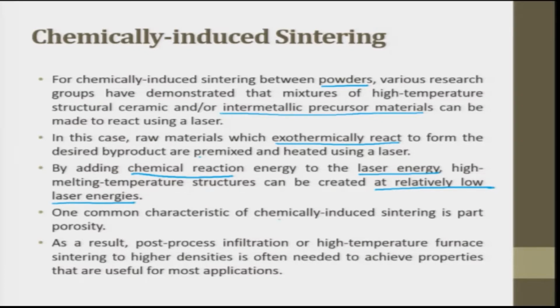One common characteristic of chemically induced sintering is part porosity, which is very, very important. As a result, post process infiltration or high temperature furnace sintering to higher densities is often needed to achieve properties that are used for most applications. Infiltration means, suppose you have a bush made out of abrasive particles. You are doing a sintering operation, and if you see here, there are a lot of porosities. These are all abrasives.